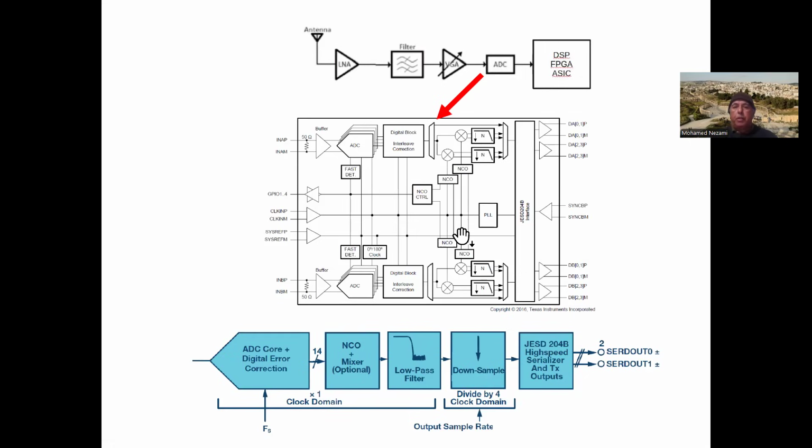And then we have low pass filtering and decimation. The decimation is necessary because we oversample the signal with tens of gigasamples per second to overcome the filtering hardship of images and nearby interferences. But once we're past that, we really don't need so many samples. So once we rotate to baseband and filter, we can reduce the signal bandwidth to the appropriate bandwidth that has to do with the symbol rate.